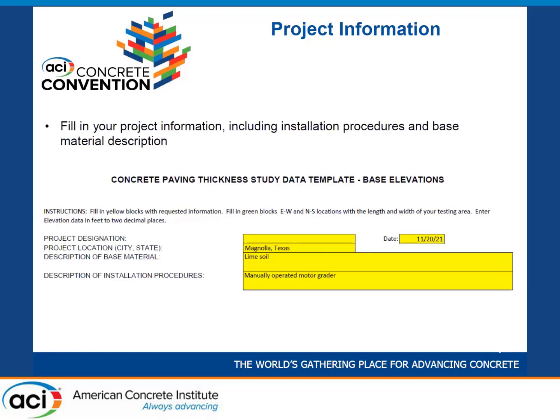We have to understand what kind of technology is being used. Where did this happen? Where's the location? What kind of subgrade? Is it lime stabilized, cement stabilized, or aggregate base? All those things matter. How is it being installed? Is it installed by a backhoe, box blade, dozer, or motor grader with 3D capabilities? All those change as you change those operations.